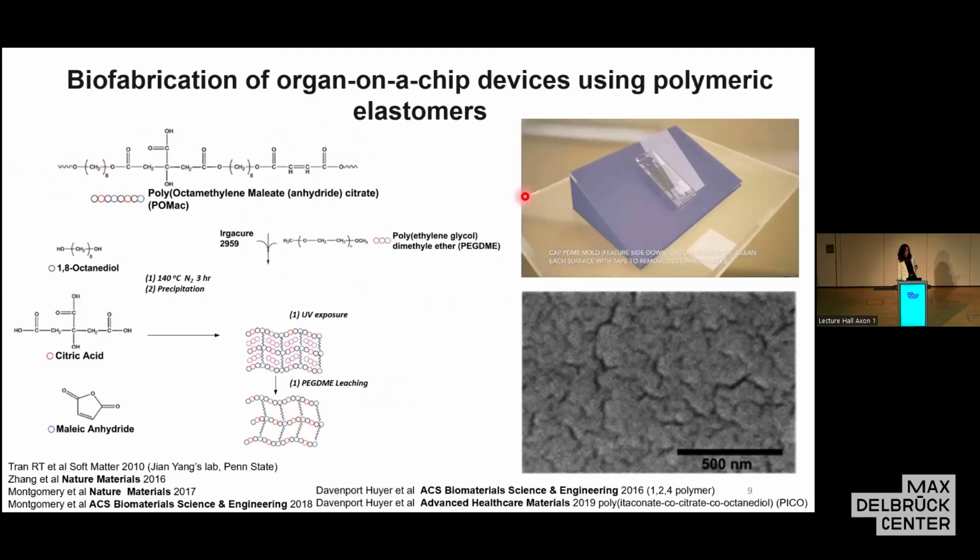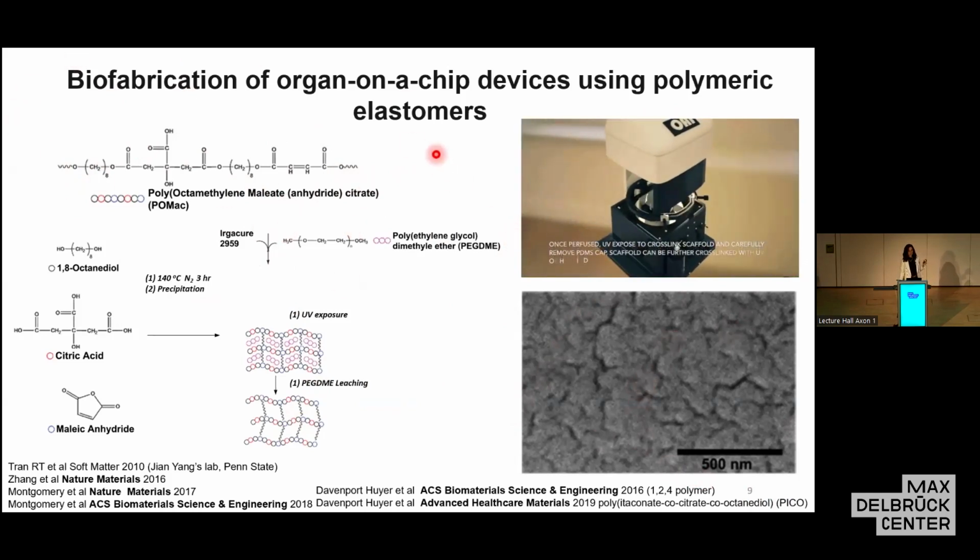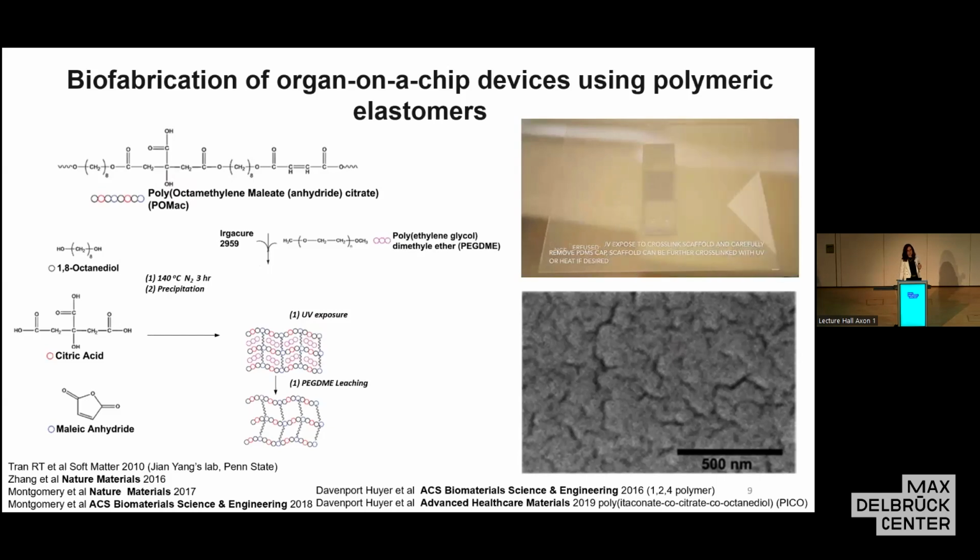And this linear polymer is viscous. And you can mold it, you can make it flow through PDMS stamps. Or you can ink the stamps into prepolymer, and by UV illumination, you can cross-link the polymer and get the shape that you like. So not only that you get the shape, but this elastomer is elastic, and we can tune mechanical properties to make it fit mechanical properties of the heart tissue.